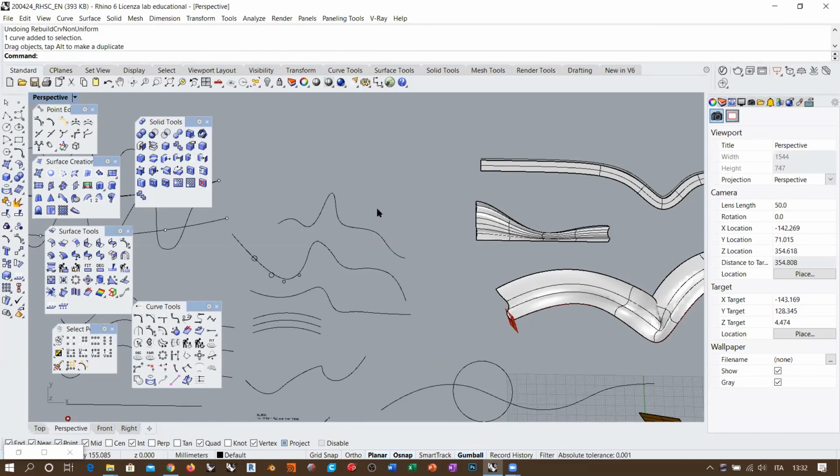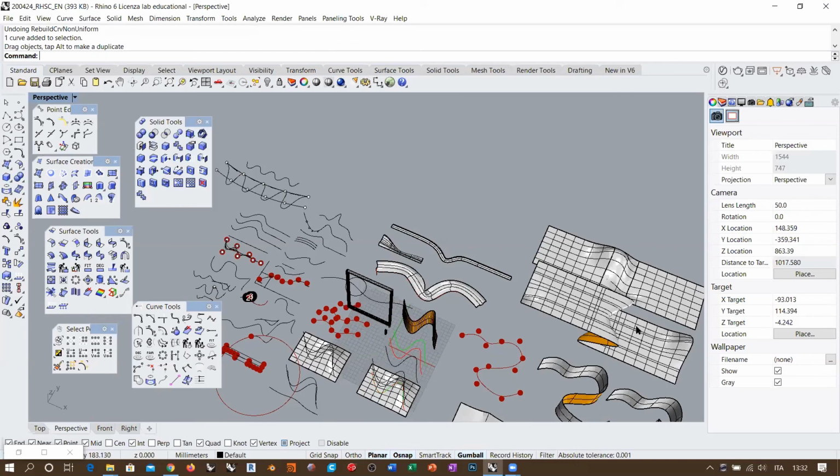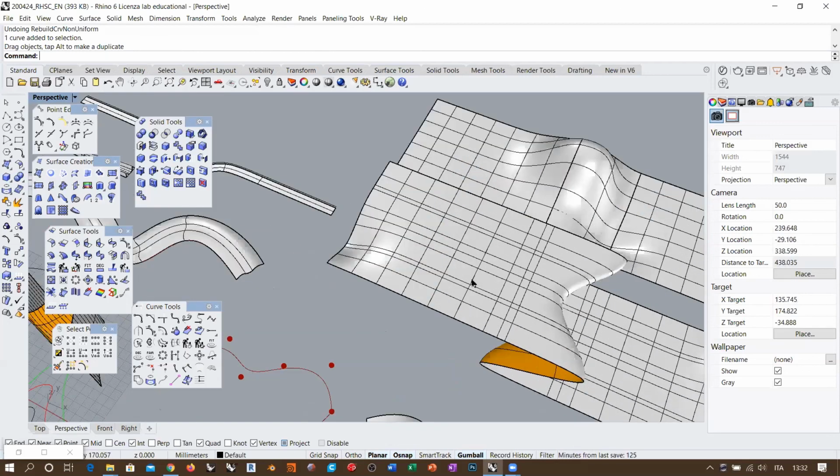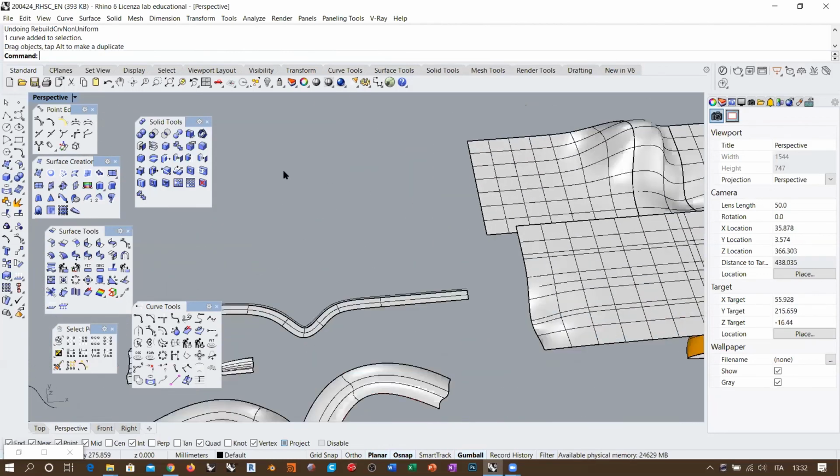And the last two questions. The first is really quick. You mentioned a type of surface where the degree depends on how many control points you have. What was the name of that surface? It's the blend surface. For how it is created, it only creates a single span surface, just as the blend curve only creates a single span curve. So the moment you create a single span curve, the amount of control points only affects the degree. Okay, that was really clear.